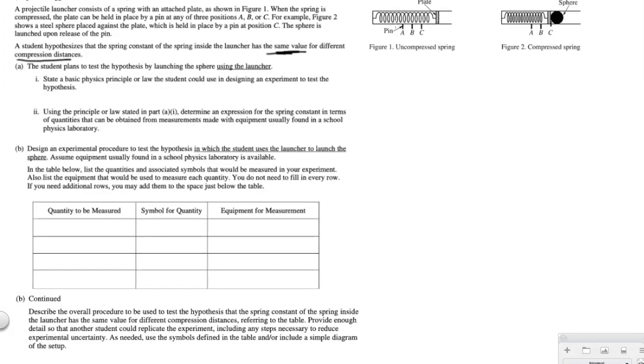And you know what? Let's just real quick review spring constant in case you forgot that. So spring constant, every spring has one. It's unique to a given spring. The fundamental equation for force of spring is the constant times how far the spring was compressed or stretched.